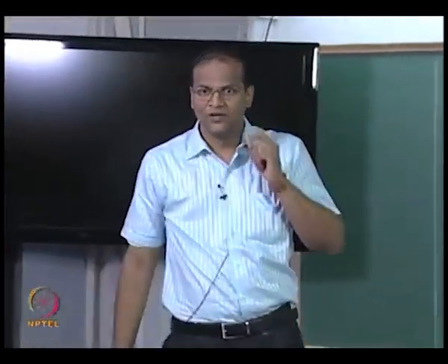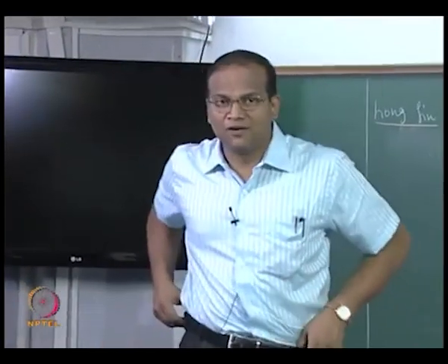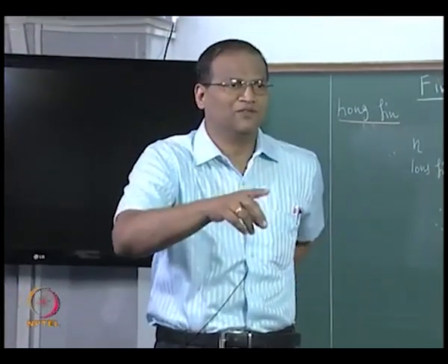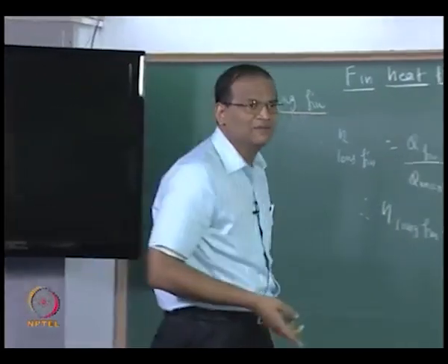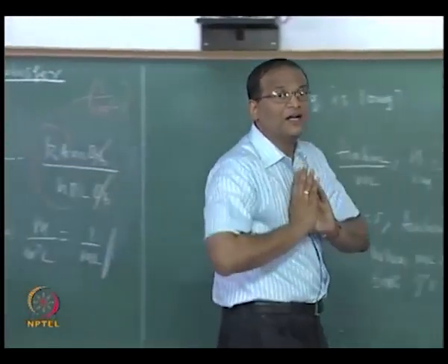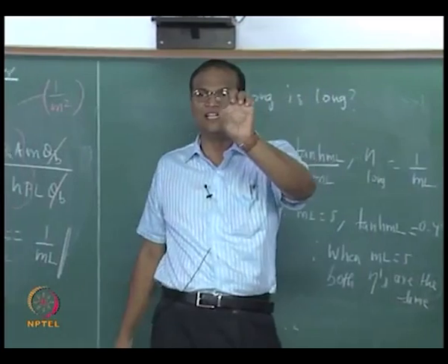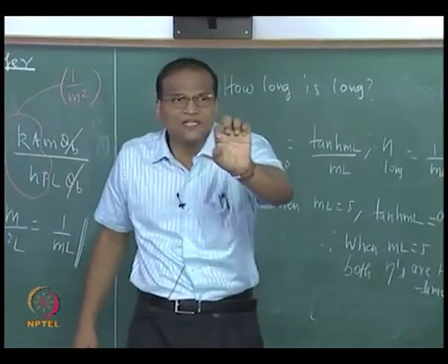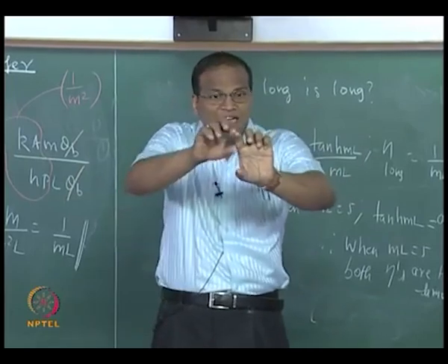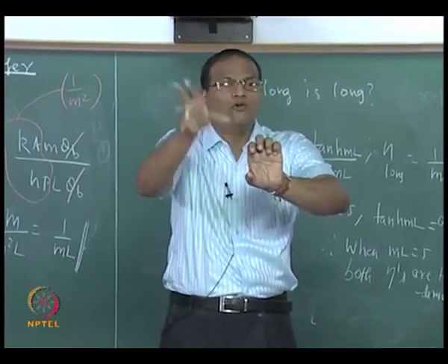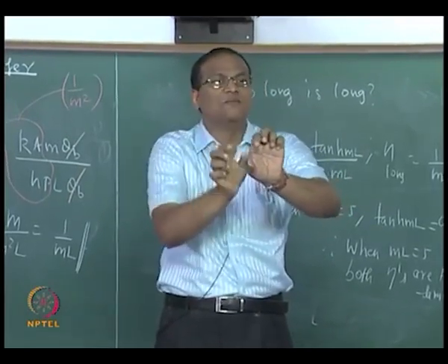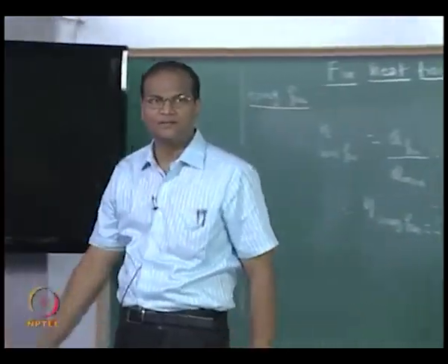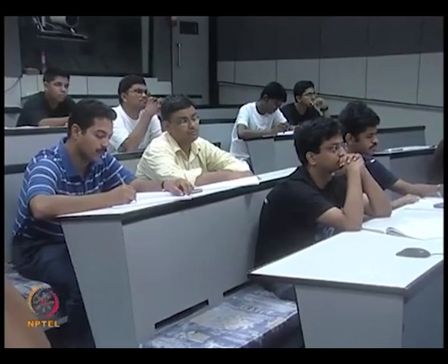Are you getting the point? So the general governing equation cannot be used to derive the one dimensional fin equation. We have to do it separately because we are lumping the heat transfer across the y direction, because we are saying that the thickness is so small that there is no temperature distribution in it. But there is a convection taking place, so how to factor it in? hP dx theta, we put it into the equation. Is it okay? All right.